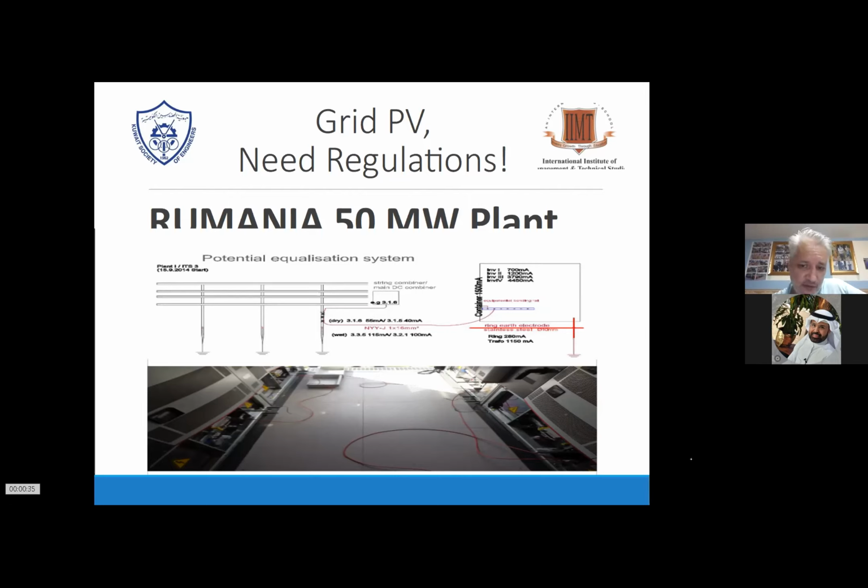And funny enough, this system was not earthed at all. You can see the red wires. These are my measuring leads, because that's the first thing I check. And in between those wire leads, you can see from 0.7 to 4.4 amps of stray currents. So those inverters are master-slave. The master-slave function did not work.